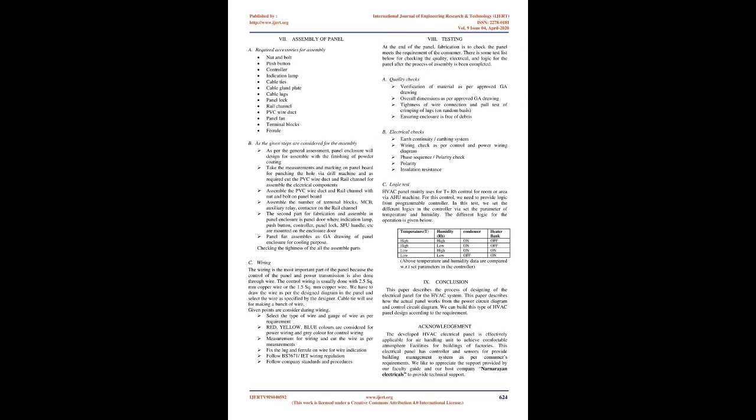Moreover, supply passes through the SMPS, which converts the power into DC supply and gives it to the programmable controller, which gives the signal to the heater bank and compressor for temperature and humidity control for the operational area or room. The temperature and humidity are measured through the temperature sensor and humidity sensor, which are connected to the programmable controller. The programmable controller will measure the result of the sensors and convert it into a digital signal.